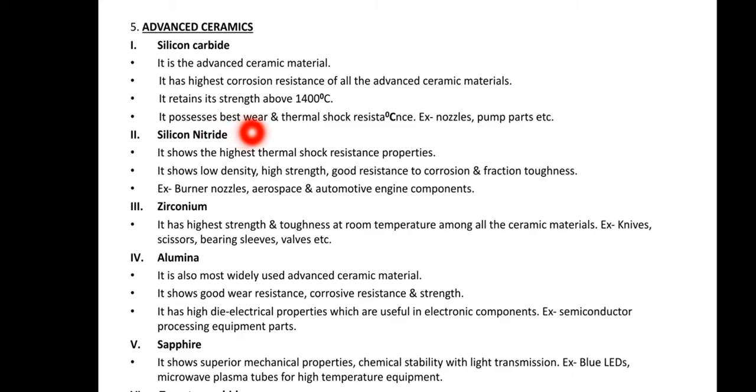It possesses the best wear and thermal shock resistance. Examples are nozzles, pump parts, etc. Silicon nitride shows the highest thermal shock resistance. It shows low density, high strength, good resistance to corrosion, and fracture toughness. Examples: burner nozzles, aerospace and automotive engine components.